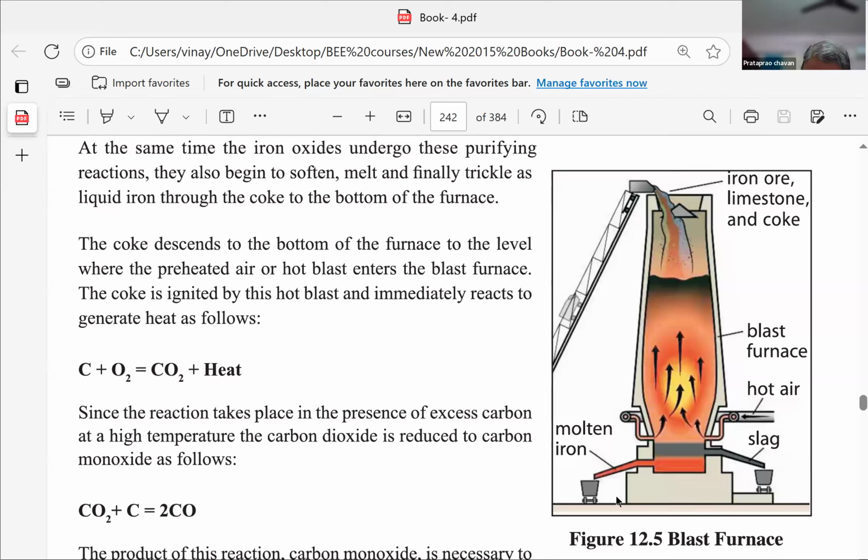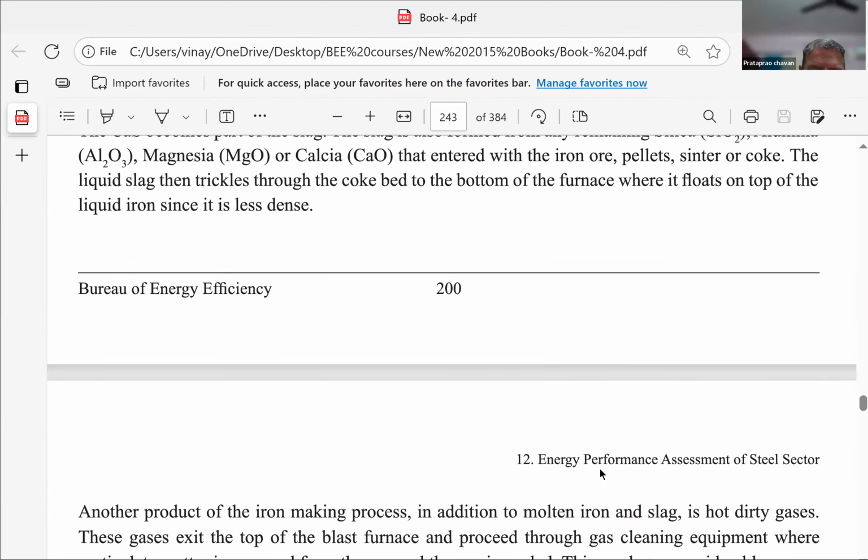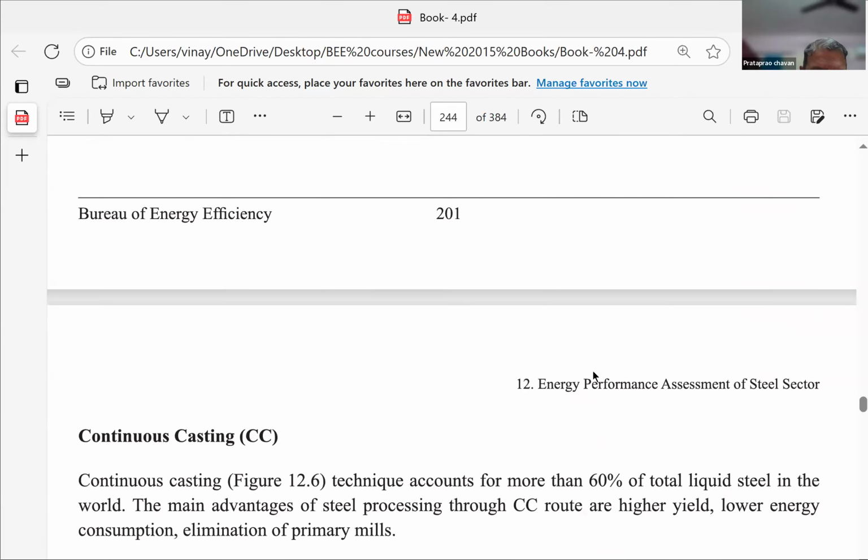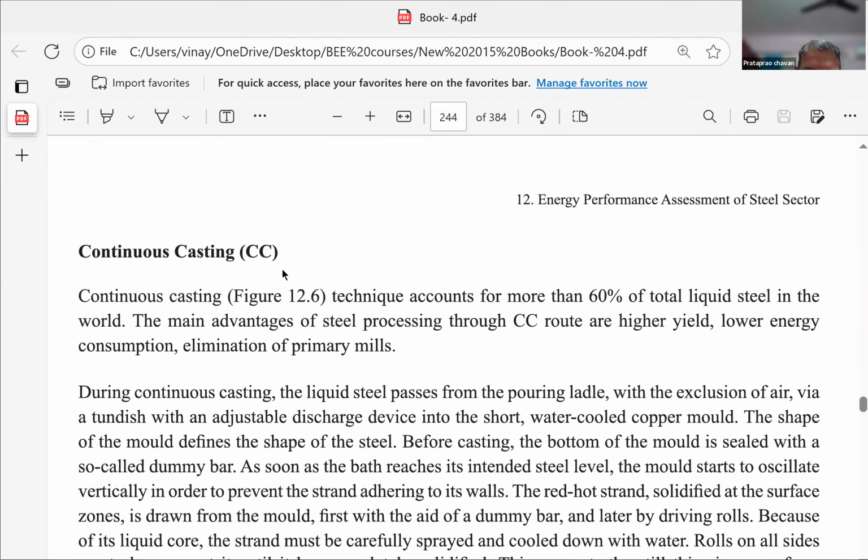Either mechanism is possible. You can keep this trolley steady at one place and move the entire train of molds slowly. So each mold, as it comes before the trolley, will be poured, the mold will go ahead, and the next mold will come like this. Or alternatively, if the molds are too big and very heavy, then they are not on the train, but the trolley is on the train and it goes on pouring. Then the trolley moves and the molds remain stationary. Either of these mechanisms, this process is called continuous molding, pouring, casting, continuous casting.